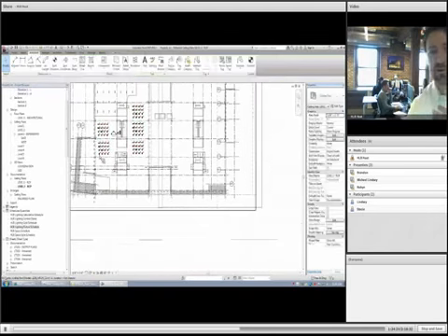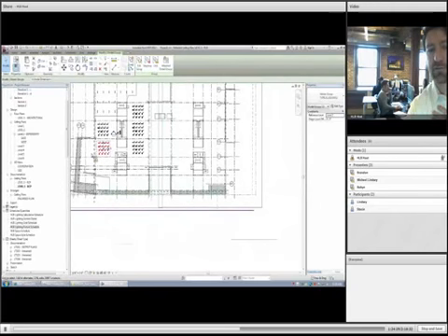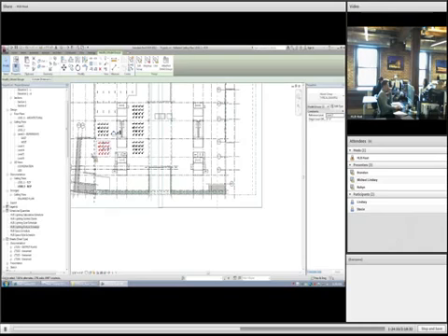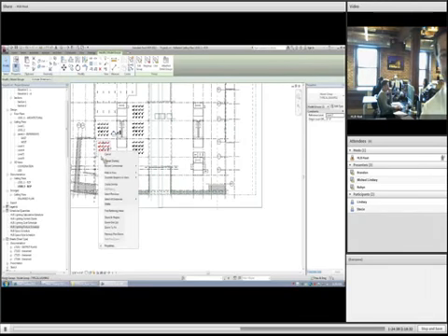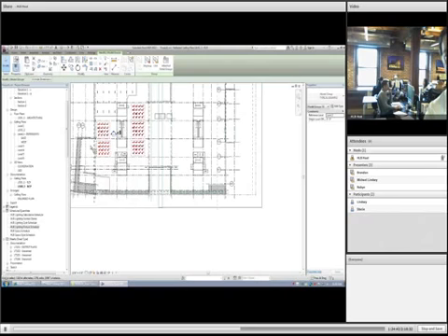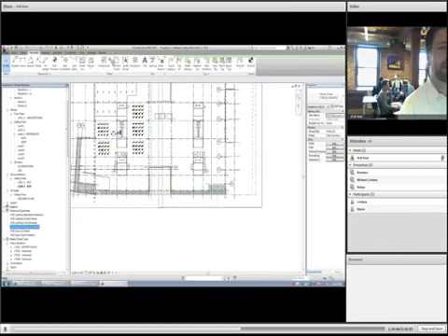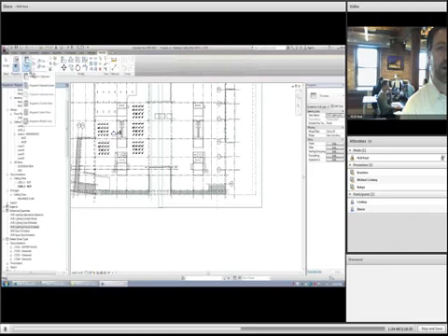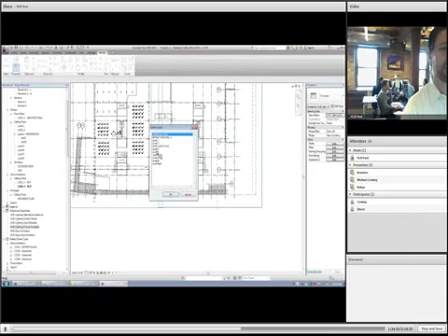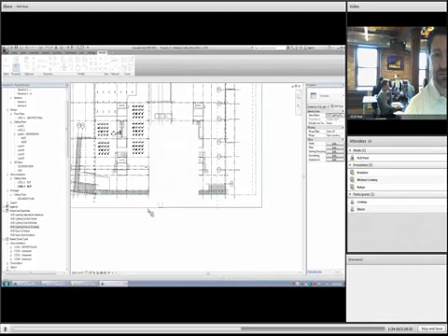Did everyone see that quick move I did to grab that group? Because I'm going to copy now to those levels. I had erased my arrays up to those other levels. Now I'm going to copy them back up. I can select one, right click, select all instances visible in view, gets them all. Control C that, and then modify tab, paste, align the selected levels, grab all of those again, shift, hit OK, and we'll paste those to the same place.